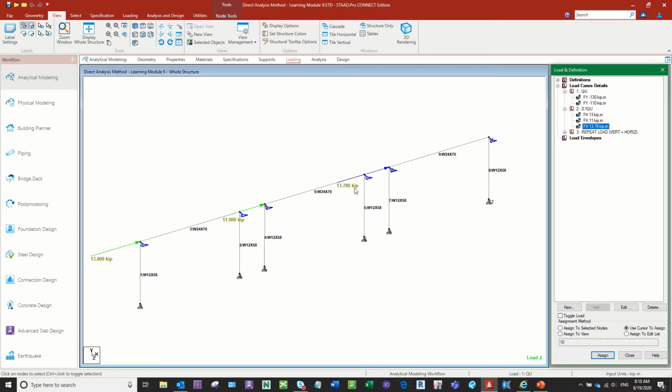And then if you also don't want to worry about the stiffness reduction, your tau sub b aspect, you can add another 0.1%. So the total of the two would be 0.3%. And as I said, it's 130 kips on that frame, so multiply that by 0.003.